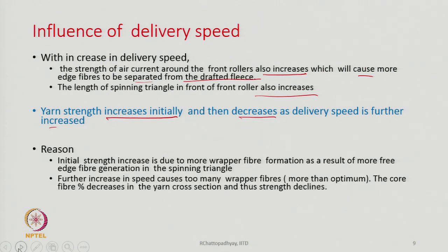The reason is, the initial strength increase is due to more wrapper fiber formation as a result of more free edge fiber generation in the spinning triangle.